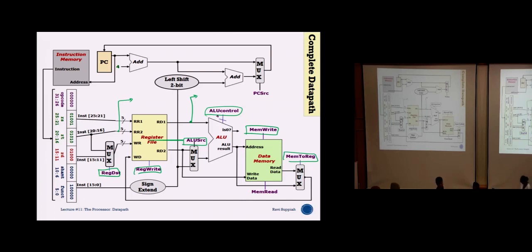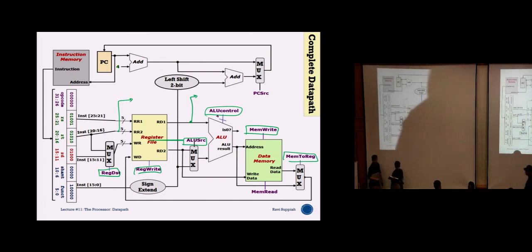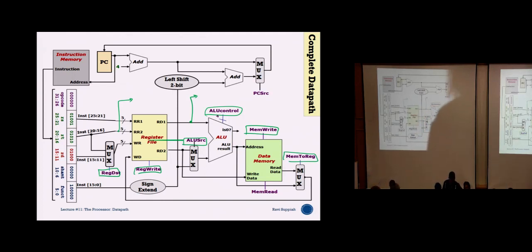But which address you store inside the data memory, do you know, or is it just random? For which instruction is it hardwired after the ALU? If it was a load word instruction or store word instruction, then the address is basically what you compute, correct? If it's an R-type instruction, then there's no memory access. You need to store into the register, so there's nothing to do with memory. If load word, I need to deal with memory: read from memory. So if it's R-type, there's nothing to do with memory. In the case where you need to read from the memory, then the data will be selected based on the multiplexer.